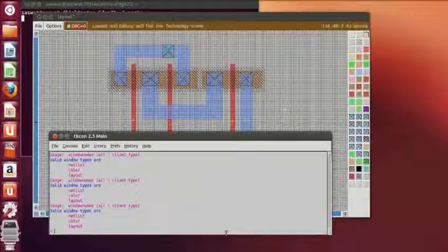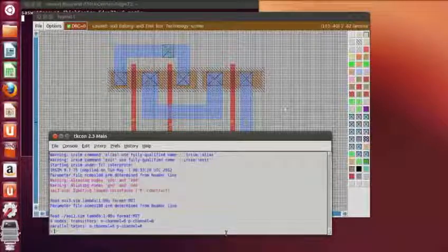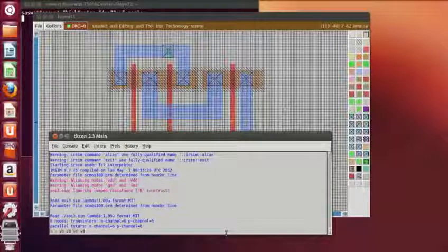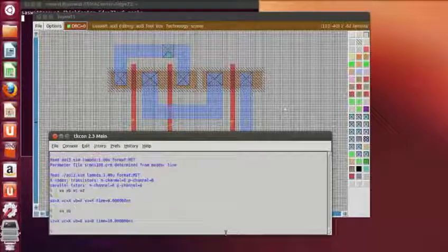Now in order to open the irsim file, we have to type irsim AOI 3.sim. Then you want to watch VA, VB, VC and VZ, the inputs and the outputs. Then display, you have the default value. If I give low value to VA and VB, I want to see the output. Since I have not given any value to C, it's showing me X as the output value.